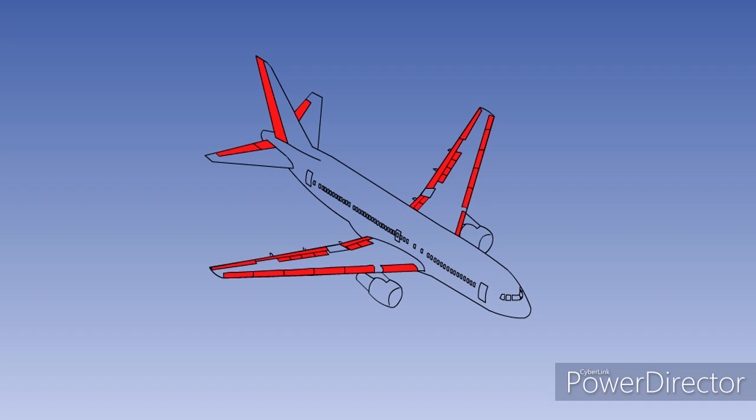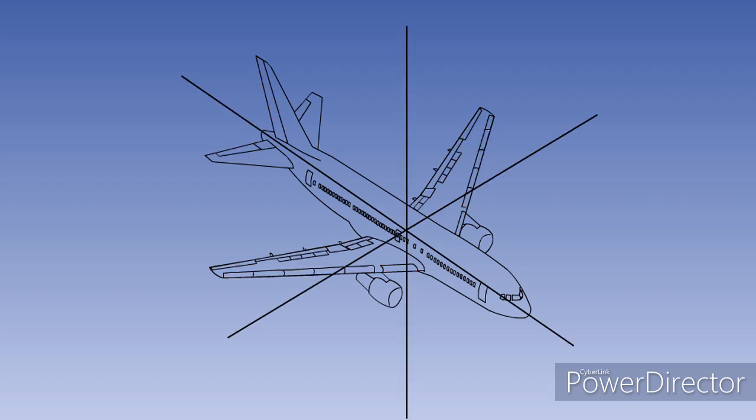In this first introductory lesson, we will look at how an aeroplane moves around its axes. For steady flight, the aircraft must be in a state of balance, with zero moments around its axes. The primary flight controls are designed to enable this to be achieved for all possible configurations and centre of gravity positions. The controls are also required to manoeuvre the aircraft around its three axes.